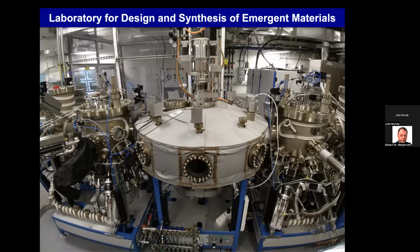Kind of related, how big of a sample can you run? This chamber is built for a 4-inch wafer, and we load a sample in on a plate. The problem is that most of these oxide template substrates are super expensive, even if you buy a centimeter by a centimeter, and sometimes we grow on even smaller fractions. When we're just testing materials, growing on 1 centimeter by 1 centimeter laterally is more than enough to measure conductivity, do electron microscopy, whatever we want to do.